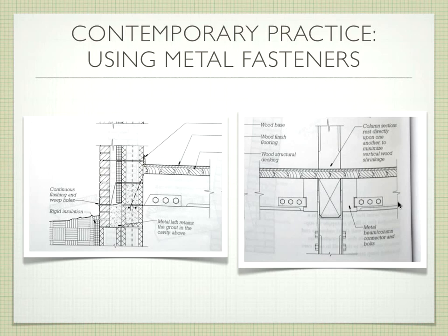Errol actually asked a great question while you guys were drawing, and he said, what about if you're mixing heavy timber and glulam? Glulam doesn't shrink because it's already dried and it's an engineered product. Heavy timber by itself will shrink. So if you're doing that kind of an environment, you still have to think through it. If this is a glulam, I'm going to run it all the way through so I know it's not going to shrink. If these are heavy timber, they're still going to shrink independently, and we need to be aware of that when we design it.